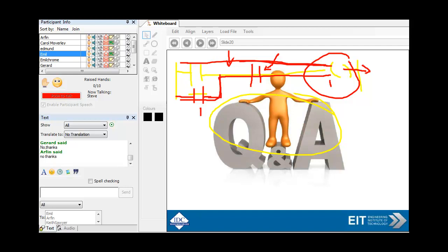So you look at the hardware, the power supply, et cetera. So things which you may think are irrelevant, like the 24 volt supply you need to standardize on. You need to make sure your supplier is going to supply PLC inputs and outputs of 24 volt DC. And then you also need to plan for things such as spare capacity in your PLC rack, so you can handle the increase in the future. So these are all issues which we're going to delve into in greater detail in the future.